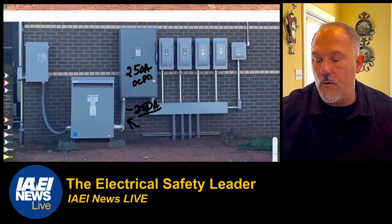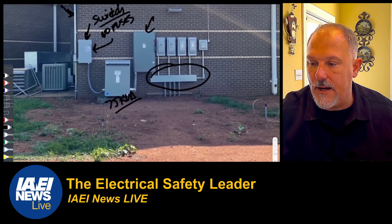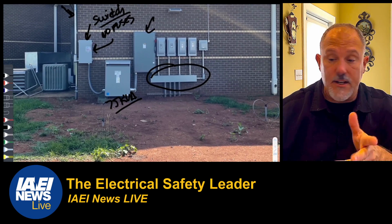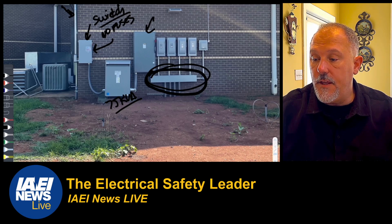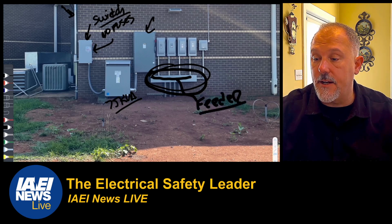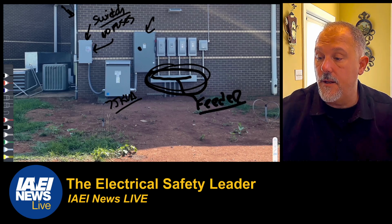So far, what we've talked about is the fact that this is not service equipment, right? So this is not service equipment. So this conductor on that secondary that's leaving that fusible switch, this is a feeder, right? It's not a transformer secondary conductor. Why? Because I have an overcurrent protective device in that fusible disconnect switch.